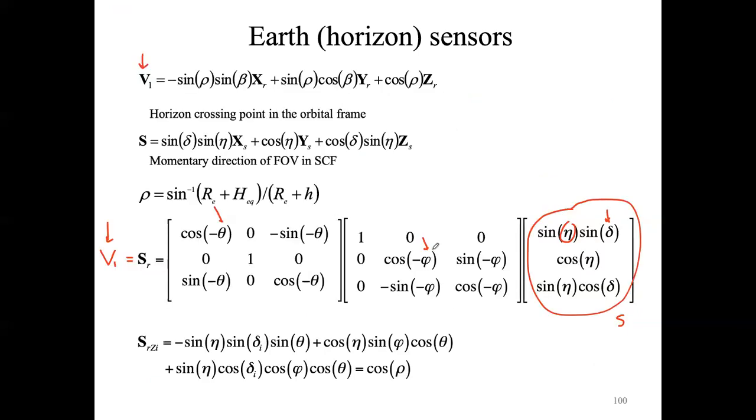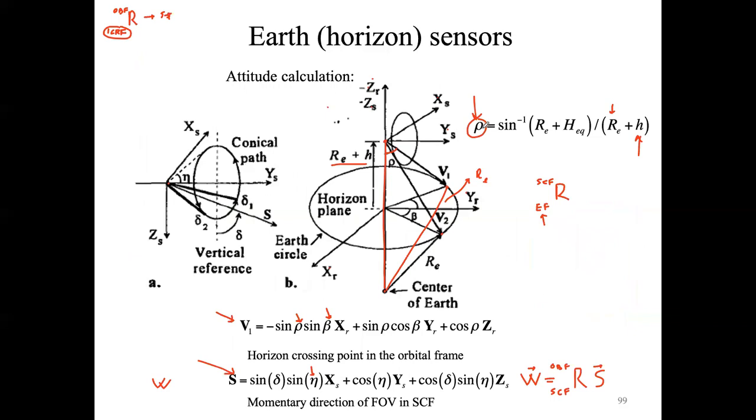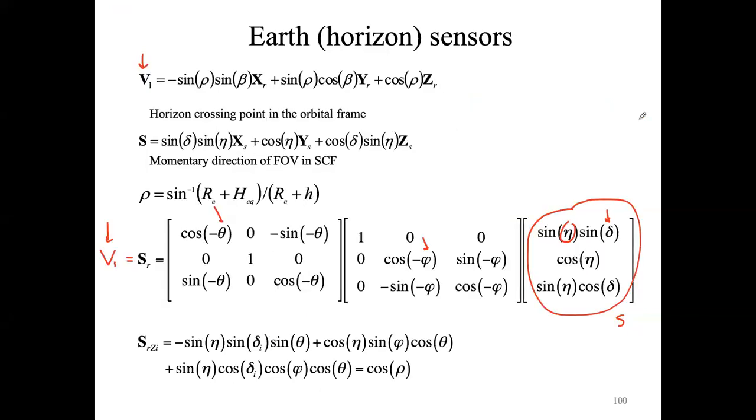So what we need to do here is that you can easily find out that in order to determine the unit vector, so basically the attitude of the spacecraft, so the angle theta and the angle phi, you have not only two unknowns, but you will have indeed three unknowns. So theta, phi, and rho. Because as I said before, rho depends on the altitude of the spacecraft.